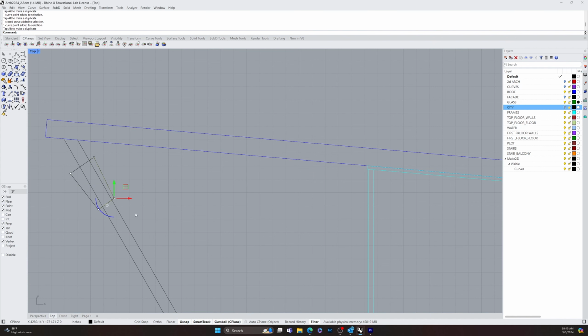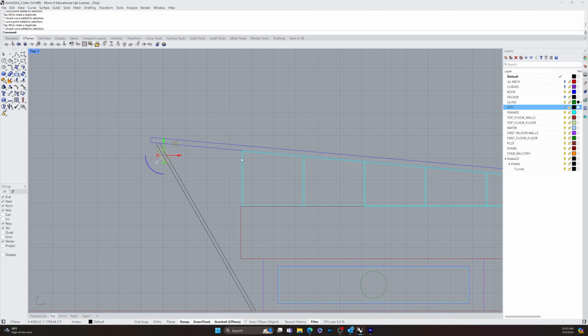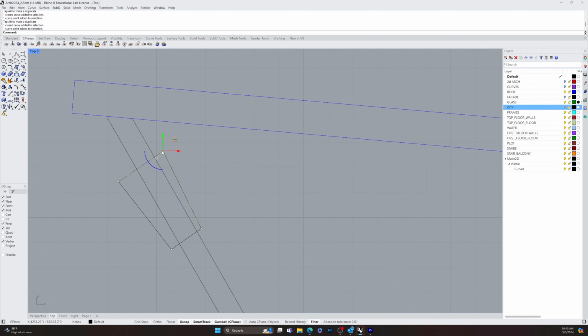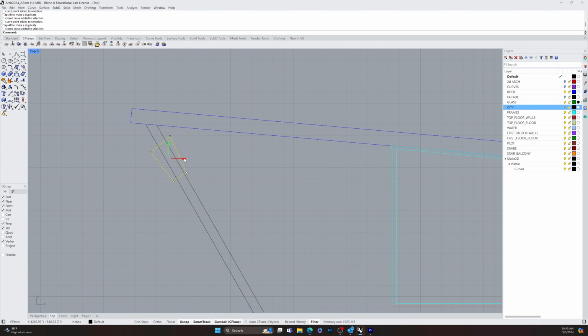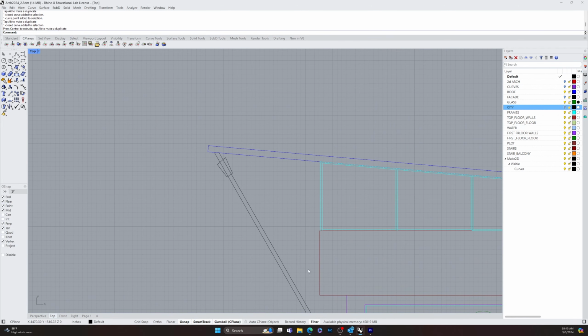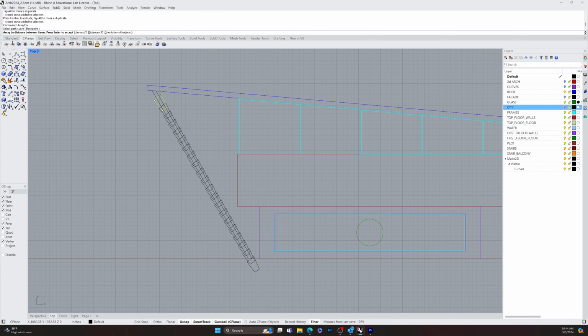So I like that it has architectural elements that are matching design details as well. I think it's kind of fun because nobody's really going to see it or know that from the get-go, just because you're not looking at the roof. All right, and then maybe I'll pull this end up a little bit like that. And just make sure it's centered there. Great. So then I'm going to array this on a curve. Select this curve. And then how many do I want? I want maybe 18. No, maybe 15.